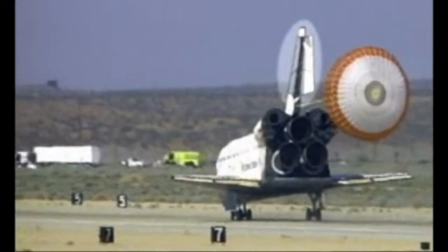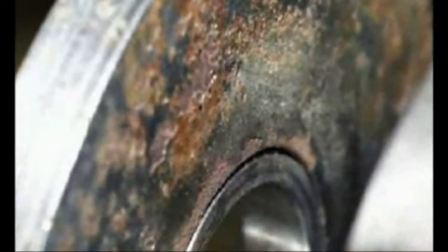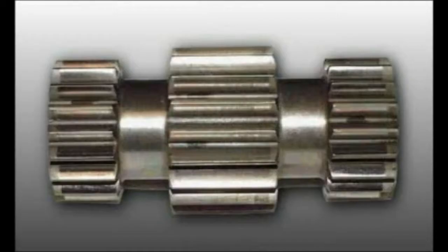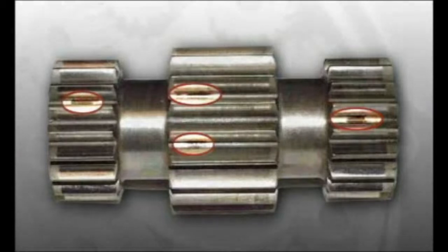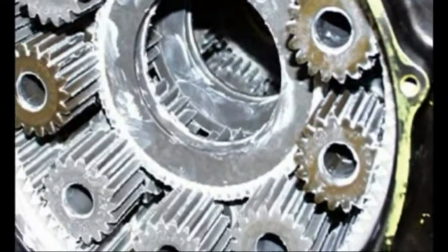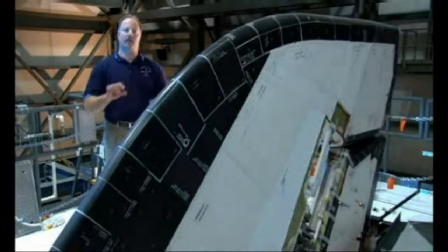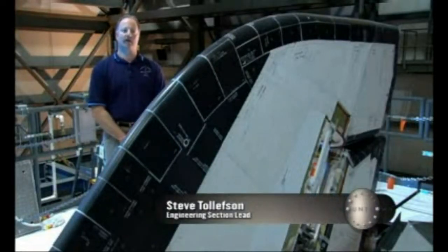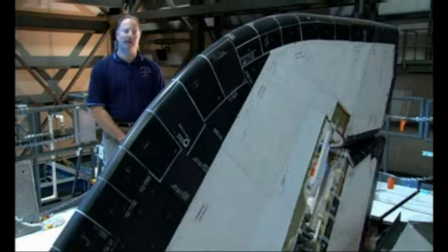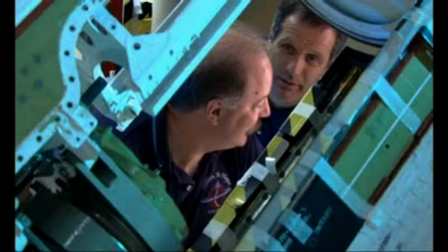During a verification inspection, corrosion was discovered on the gears of the actuators. While investigating the corrosion, unusual wear and tear was noted on the gear set, leading to the discovery that the gears had been reversed during installation. There are two sets of planet gears, and they have been installed in the reverse direction from how they should have been. Basically, they've been swapped out.